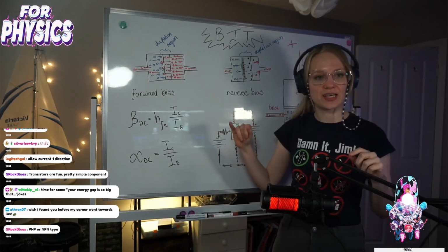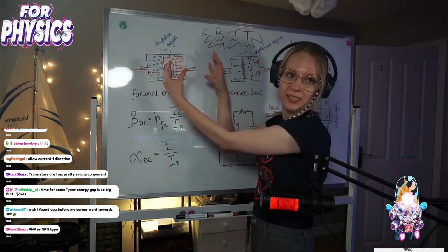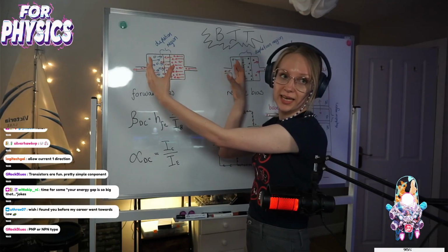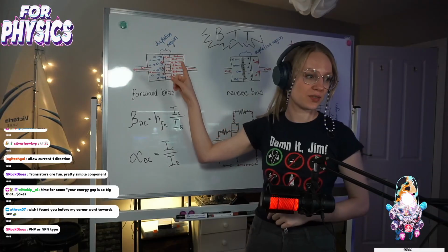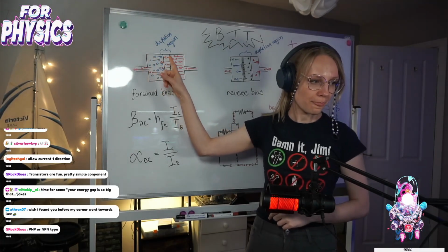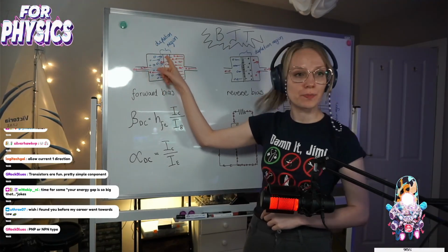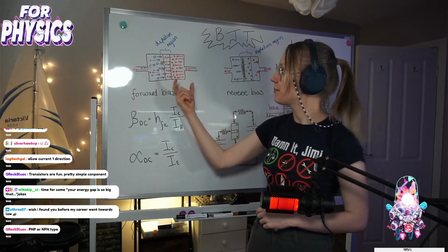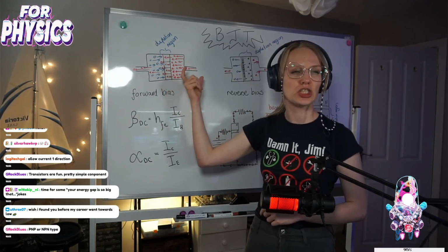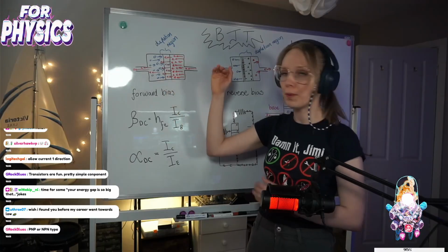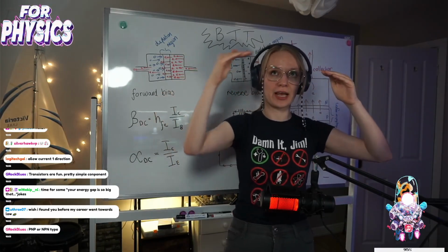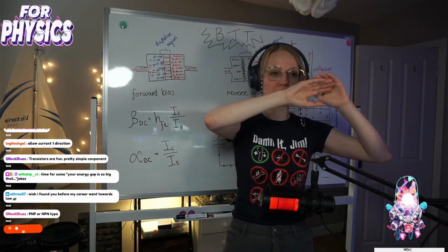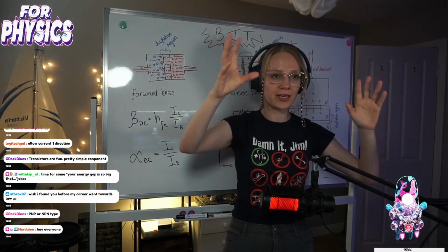So what that means is that when we put these two different doped materials together, very, very quickly something called the depletion region is developed over time. When we have a depletion region that's developed, it means that there is an electric field, a huge potential buildup. A whole bunch of electrons and holes come across first. Every time an electron meets a hole, there's a pair annihilation occurring.